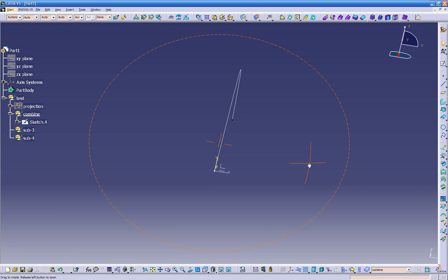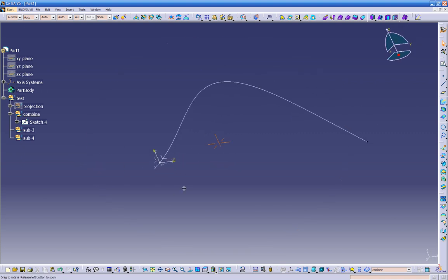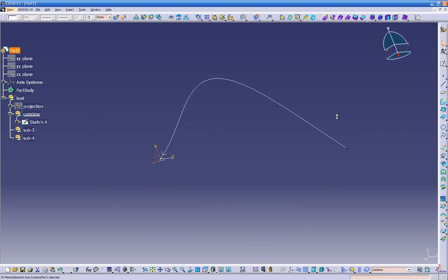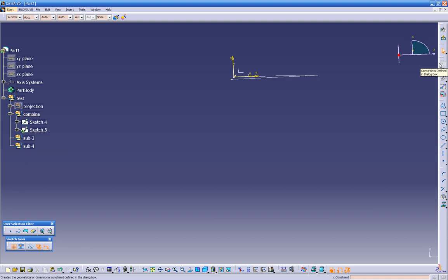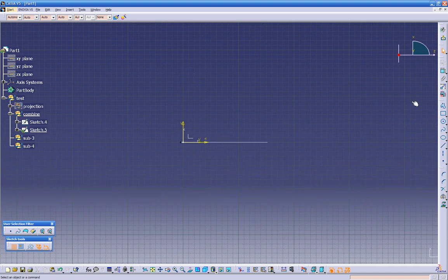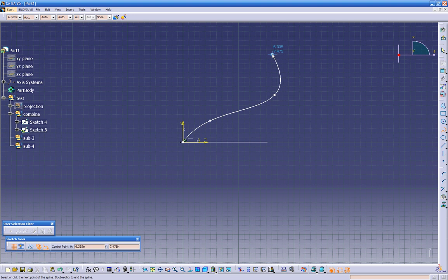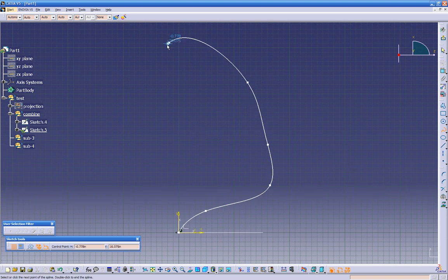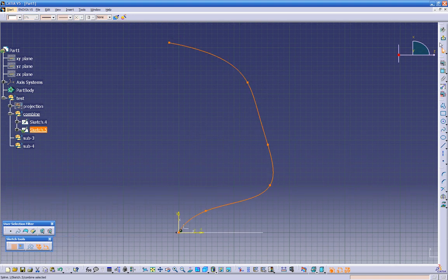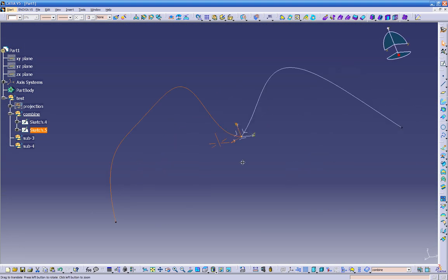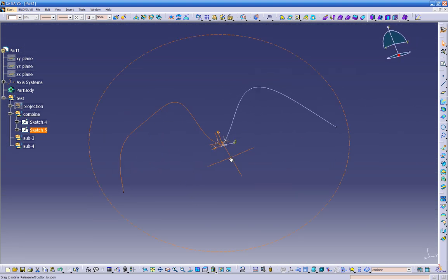And let's create the intersection, another spline with Z and X. Okay, you can see better this way. So let's click on this plane and let's create another sketch. Now let's go back to the spline. Let's go back to the origin. Let's get out of the sketch now. So we got